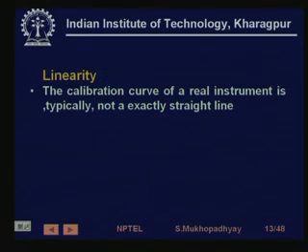If you have an instrument sensitivity of, let us say, 10 millivolts per degree centigrade, then if it gives a 25 millivolt signal, you know that the temperature is 2.5 degrees centigrade. You can get it just by dividing by a number or sometimes adding another number to it. So from the point of view of usability, it is very attractive to express the characteristic as a linear one.